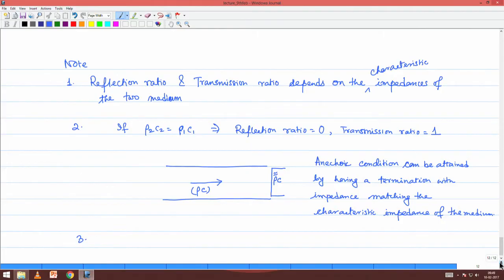So, by creating reflection, the muffler has partially reflected the noise back to its source, and that is not a problem because the receiver is getting saved. The receiver is having lesser noise to deal with. The philosophy is you reflect back the noise to its source and thereby attain your objective. So, that is the principle of design of reactive mufflers. I will come to mufflers in great detail later, but I just wanted to make this comment.